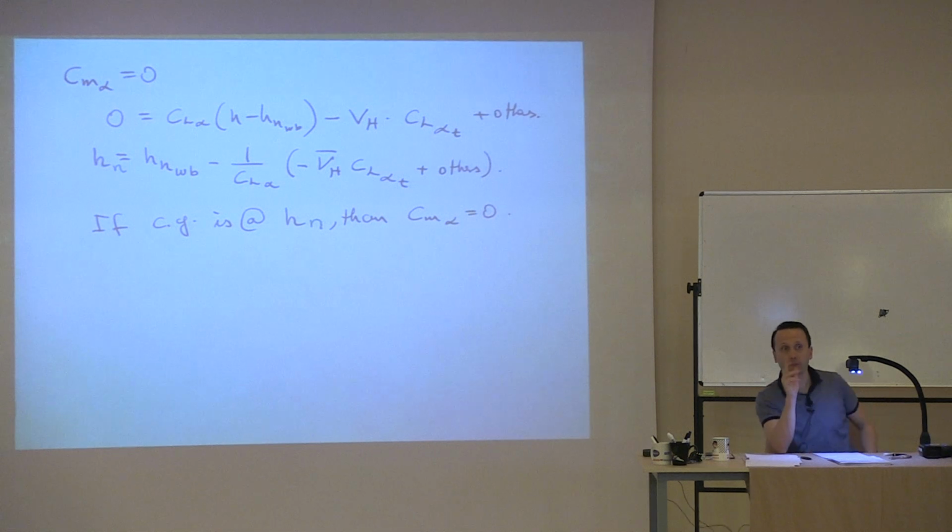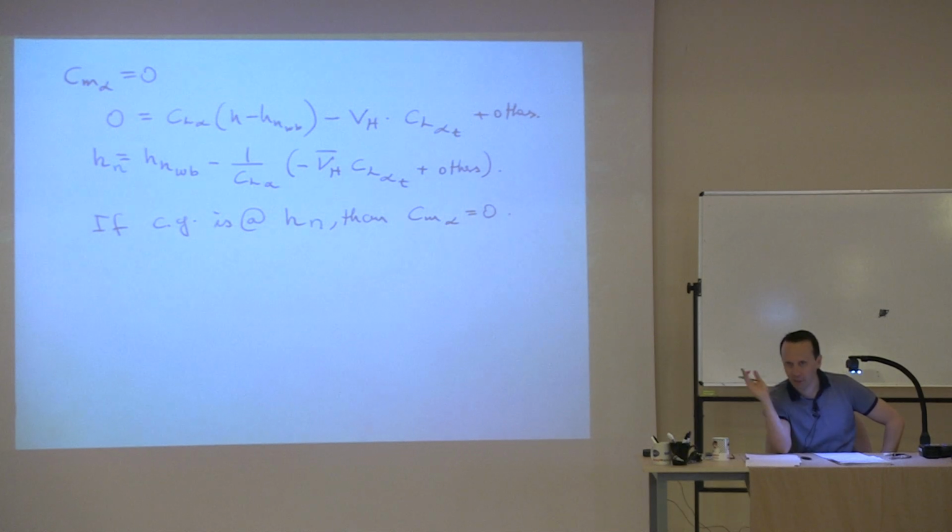It is a point. Now, the definition has changed a little bit because now we have a center of gravity. In the airfoils or in the wings, we really don't talk much about the center of gravity. We just say it's the aerodynamic point. If you take the moment with respect to that point and you change the alpha, the moment will not change. That's purely because of the geometry of that wing, right?